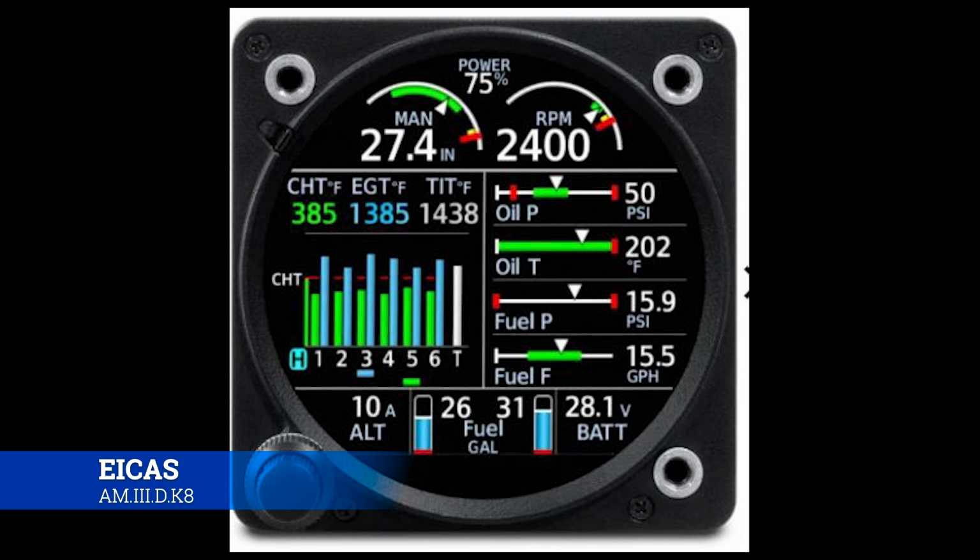That means that the RPM is sitting right there at the 75% mark, and you've got about 25% more that you could potentially get out of it, but you're not going to get that much more. The likelihood is that's probably about the most efficient place for the engine to be. So typically you're going to cruise at about 75%. You have your manifold pressure on the left right below it with the RPMs right there. That tells you all your engine power. It's not a quadrant, but that section above that white line is all about engine power.